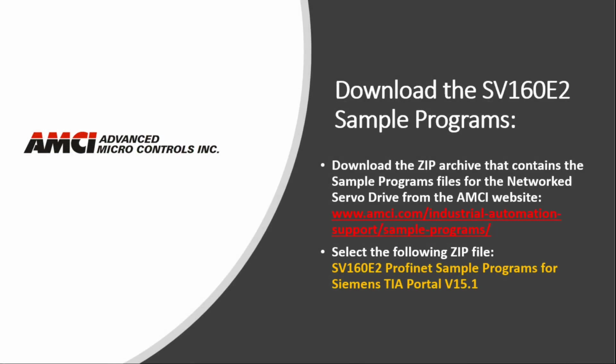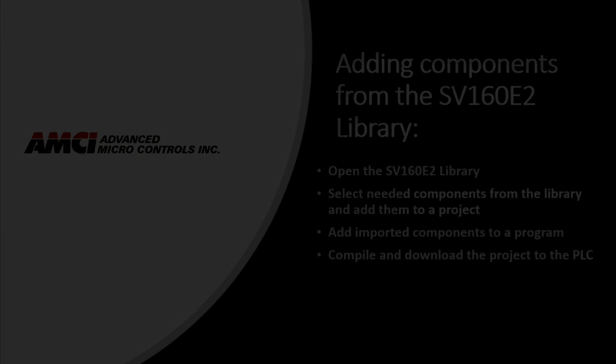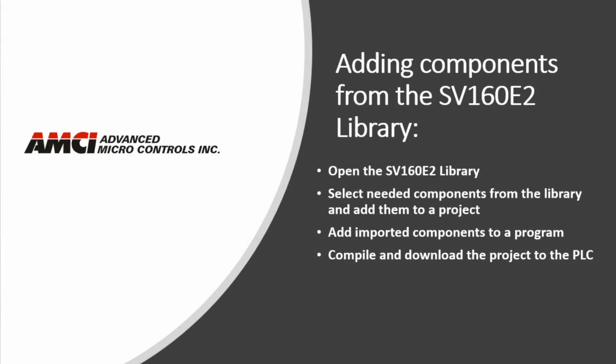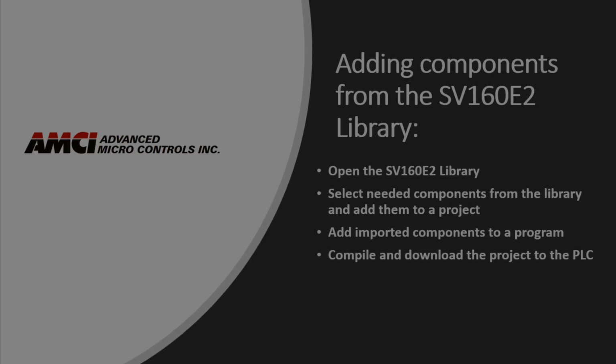It is recommended to download a zip archive file that, besides sample programs, contains a library with many components such as functions, data blocks, and PLC tags, which will be used in this tutorial, and it will definitely make your programming efforts easier. Now we're going to open the library, select all needed components from the library and add them to the project. Then we're going to use all those important components and build our program for this tutorial, and then we're going to compile and download the project to the PLC.